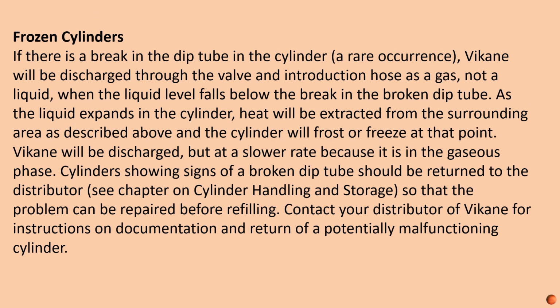Frozen cylinders. If there is a break in the dip tube in the cylinder, a rare occurrence, Vikane will be discharged through the valve and introduction hose as a gas, not a liquid, when the liquid level falls below the break in the broken dip tube. As the liquid expands in the cylinder, heat will be extracted from the surrounding area as described above, and the cylinder will frost or freeze at that point. Vikane will be discharged, but at a slower rate because it is in the gaseous phase. Cylinders showing signs of a broken dip tube should be returned to the distributor.